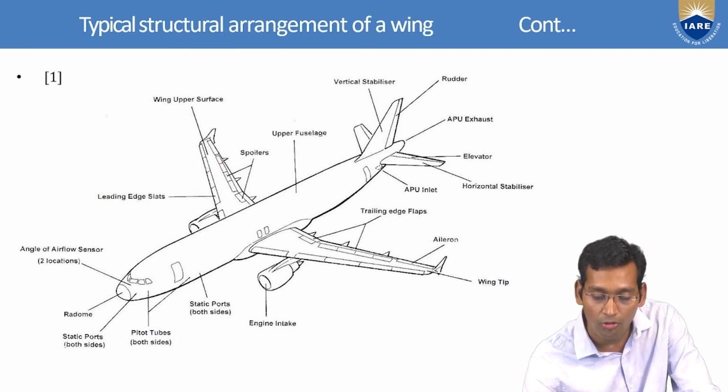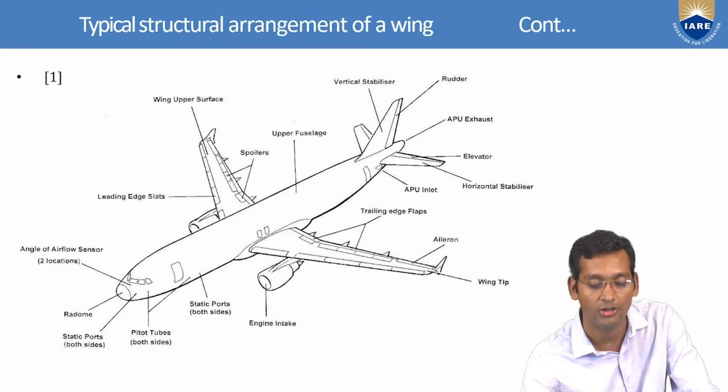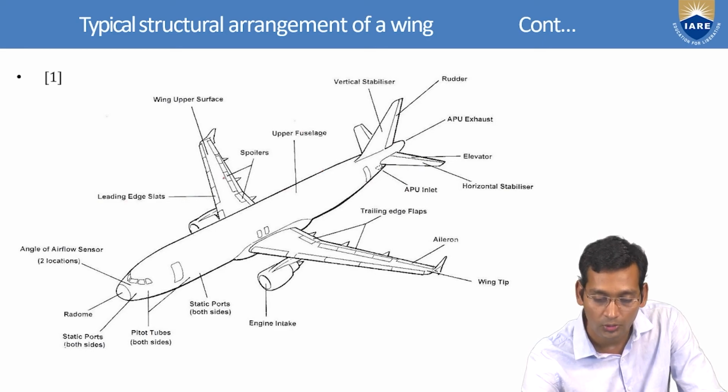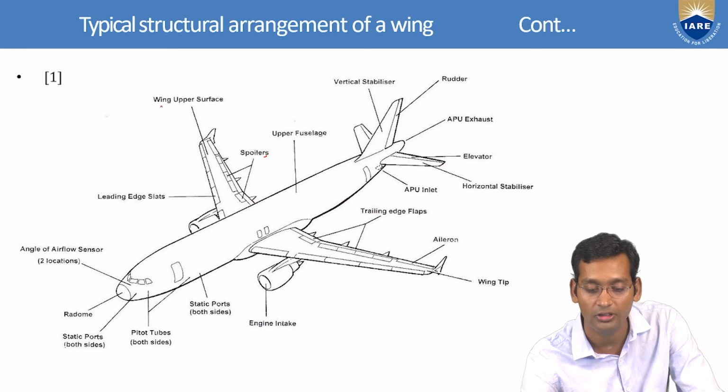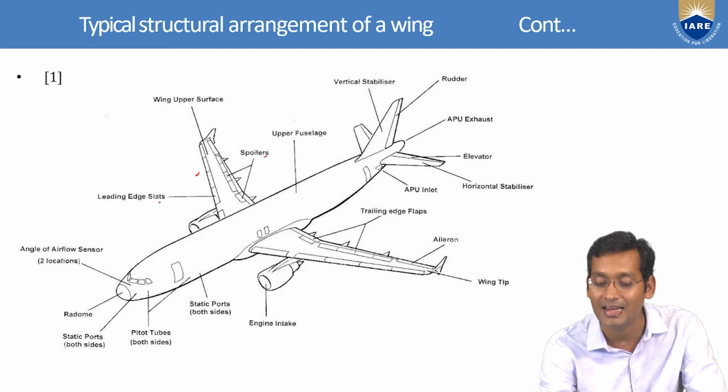So these small cuts over the wing, at the backside, which are flapping over this one, are called spoilers. Okay, just see here in this image clearly. So here these are spoilers over the upper surface, that is the wing upper surface, not this side. Again, just see this side, the cut part is there that is moving depending upon the adjustment. So this is the leading edge slat.